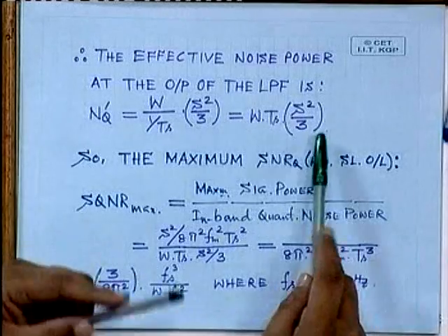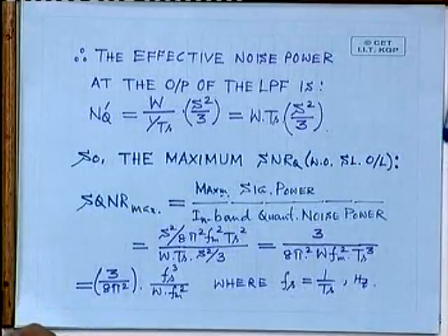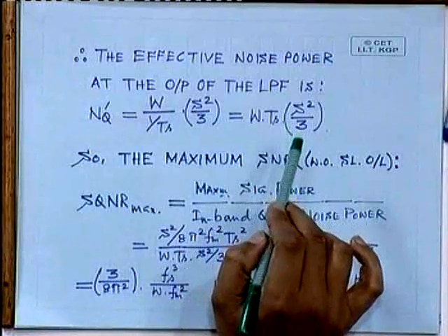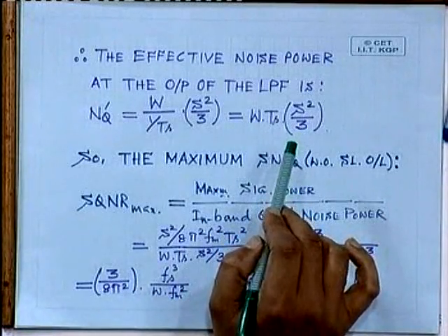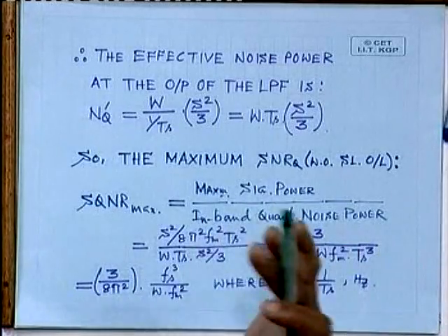So, is that an advantage or a disadvantage? You should always put a low pass filter at the output of your demodulator, the delta demodulator. If you have not done that in your lab experiment, please do that. And the design of that low pass filter really matters. One should not design just a very casual second order filter, because then you will pick up a good amount of noise, especially when the sampling rate is not very high.